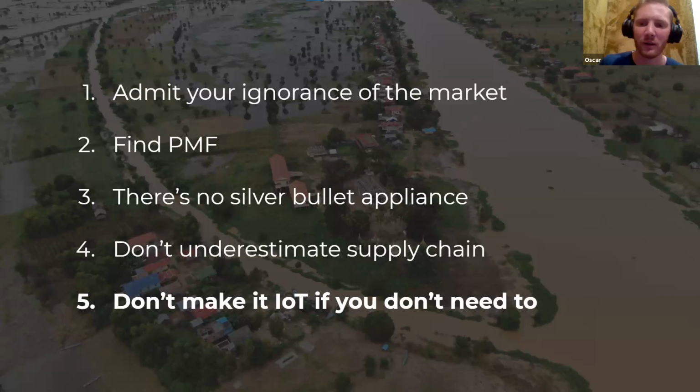When you add devices that send and receive radio transmissions, that makes both the design and the supply chain really, really complicated, because radio transmission devices are heavily regulated in most countries. And depending on the country, if you're trying to import a product that communicates via 2G network, you're going to need a whole host of approvals, tests, certificates. You need to prove that it meets certain standards of what's called EMC, or electromagnetic compliance.